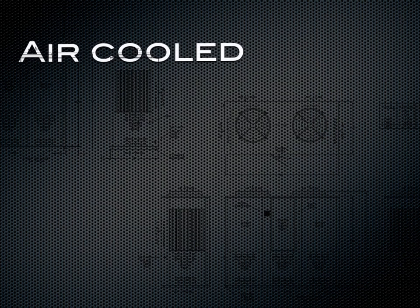I want to go over a couple quick things about an air-cooled chiller you might want to know. There is minimal maintenance on an air-cooled chiller. On the condenser side, as long as you keep those coils clean and you keep your fan motors running, there isn't much maintenance compared to a water-cooled chiller.